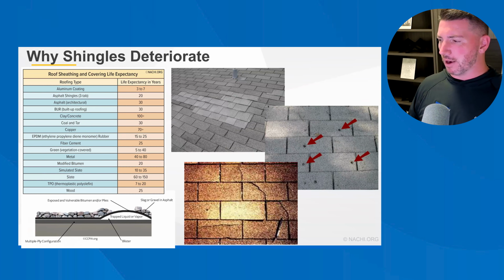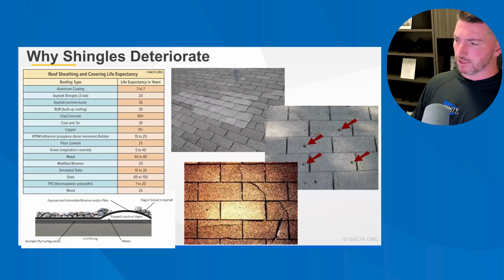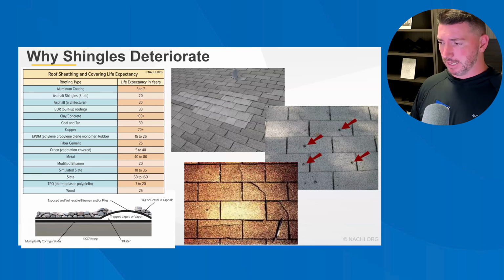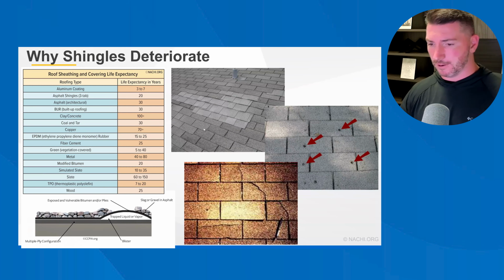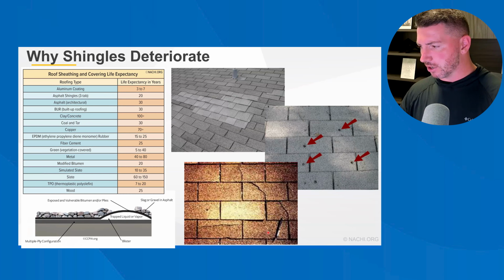The ones on the bottom with those vertical tears, I would say that those are just vertical stress fractures, and they happen basically because of the stair step method of installation here. I'll quickly just show with a laser pointer that this shingle, this full shingle got installed.